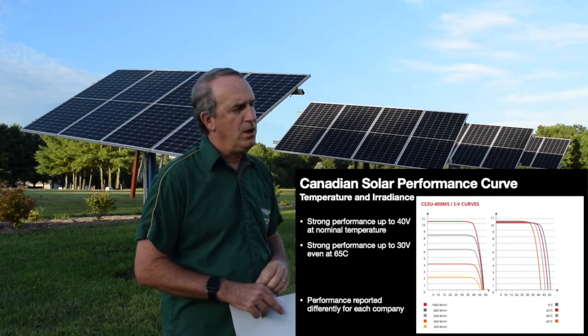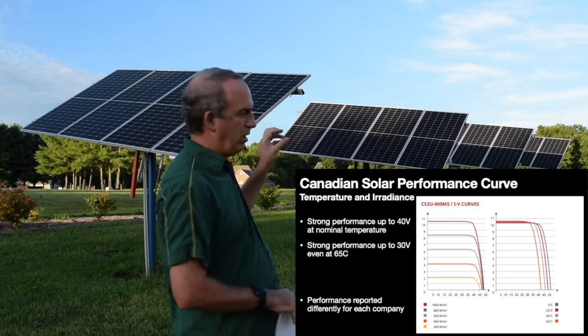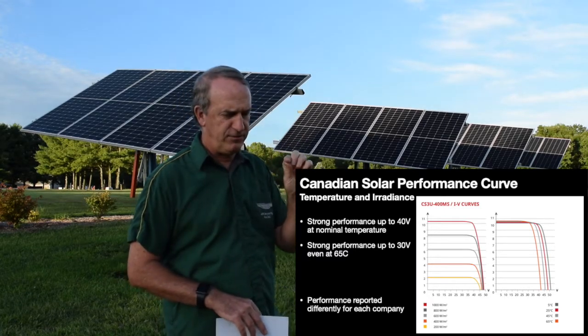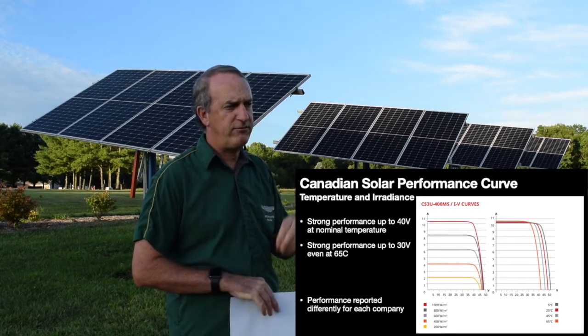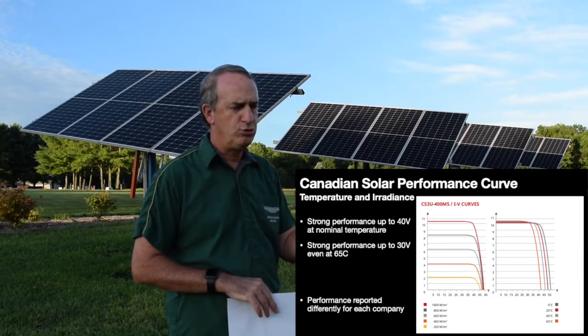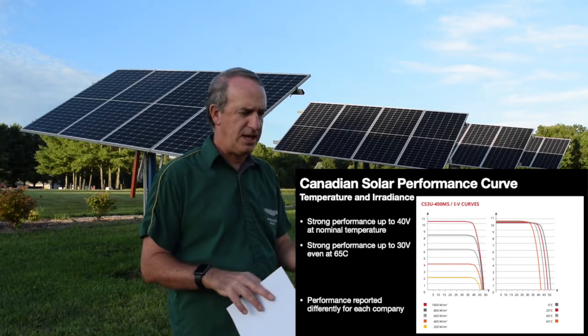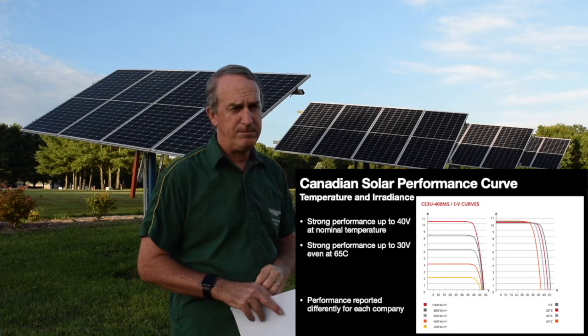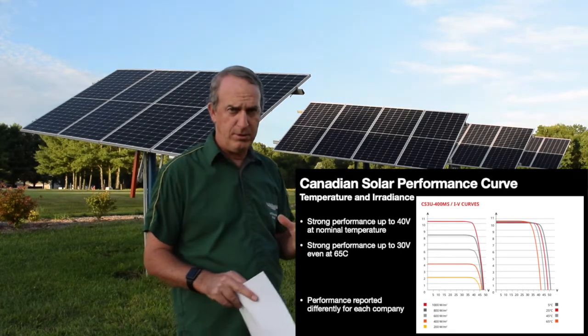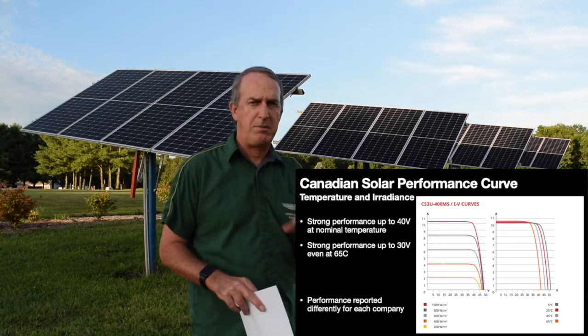Now, what we talked about before is that that's how much power you get, and that's not exactly true. Solar panels are less effective with less power than they are with full power. So as you have less and less power, you lose more. At 70% irradiance, you might get 60% of the power. That number changes depending on the panels that you buy.